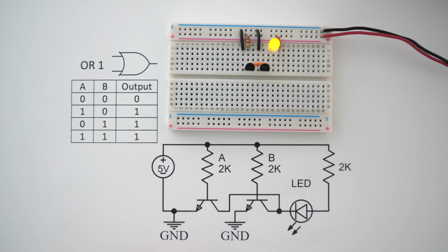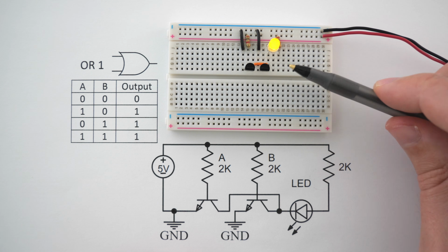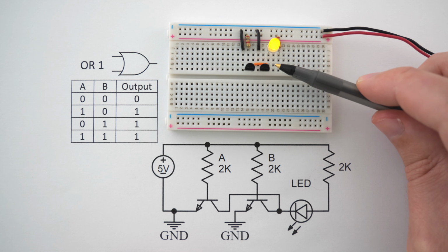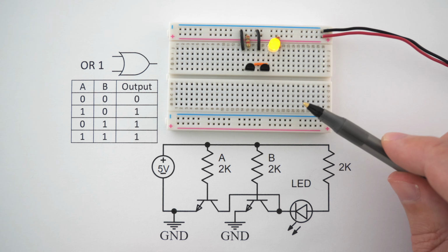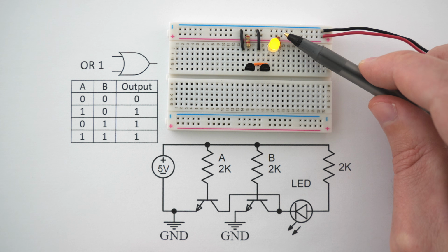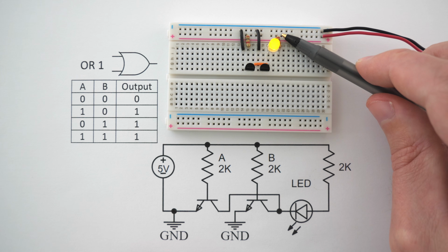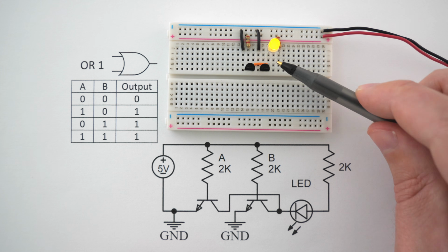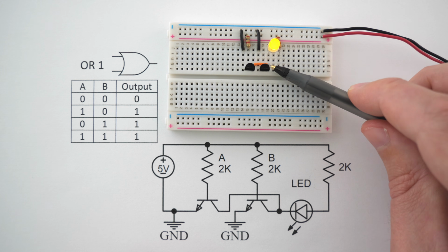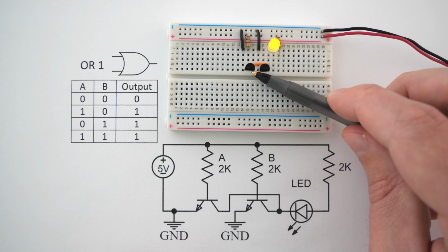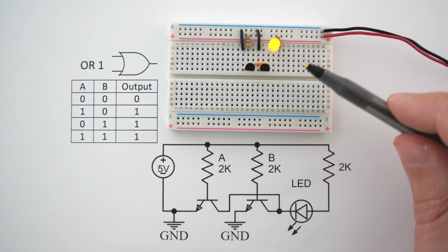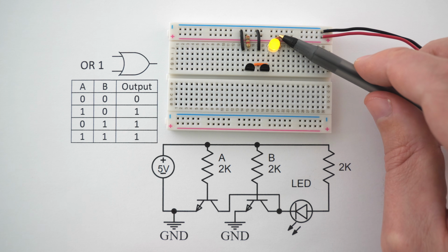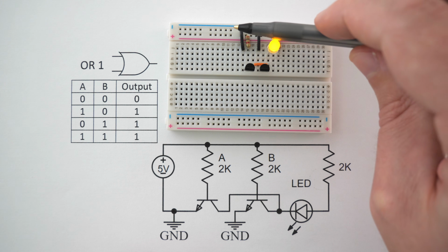Now let's look at how this circuit is actually laid out. You'll notice that there's this orange jumper, which connects the collectors of both transistors together. What this allows for is whenever there is current flowing from this positive 5 volt rail, it goes through this LED and then into the collector of both of these transistors. This makes it so that only one of these transistors needs to be turned on to allow current to flow from this positive 5 volt rail to one of these grounds.